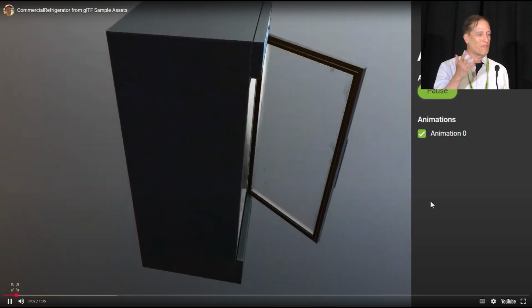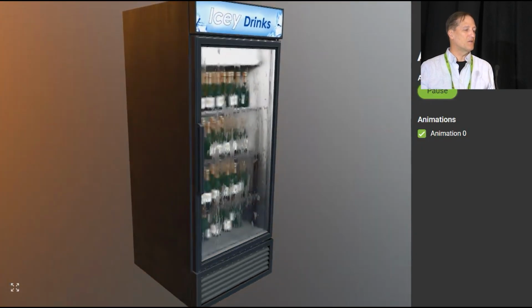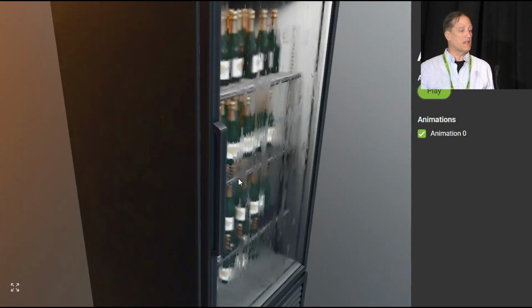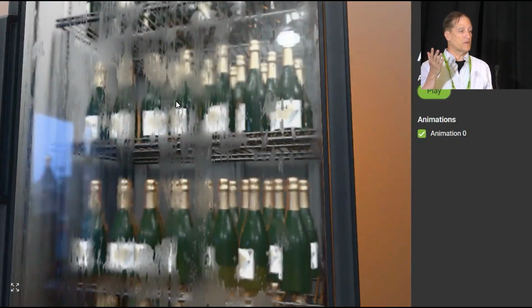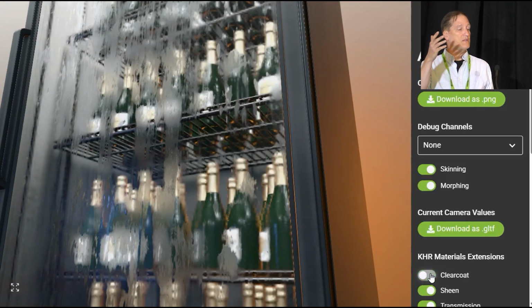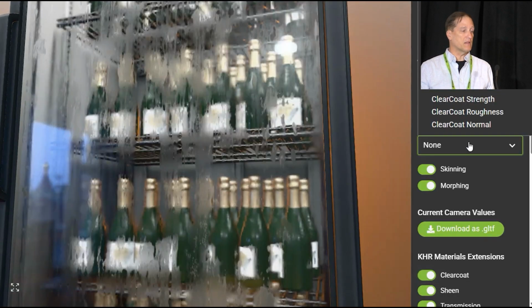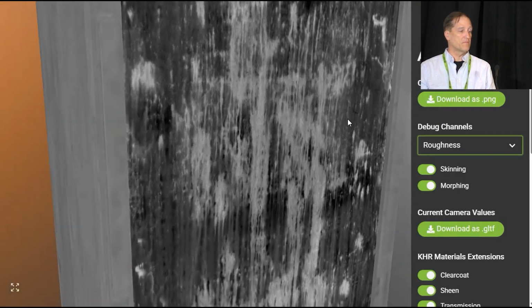And then the refrigerator, that was basically, I would love to do something that has condensation on the glass. I thought that'd be fun to try. So this just uses roughness on the glass, and the transmission effect uses the roughness of the PBR surface to decide how blurry the transmission is. And so that's a really quick way to get something that looks like condensation. But then, because you're using the roughness, you don't get that smooth glass surface on the outside. So I just added clear coat on top of the glass, and you get that secondary sharp specular response from the glass.